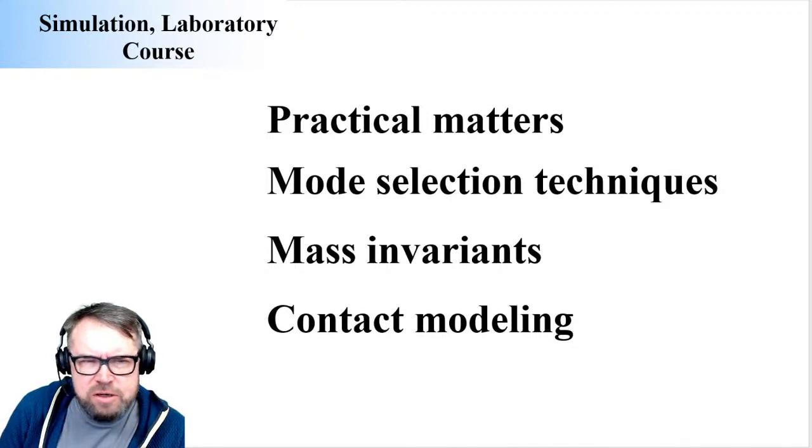Those two things are how to do this mode selection. So we know how to compute these assumed deformation modes. We know that we can do that by using an eigenvalue analysis, or if we want to be more advanced, then we can use the Craig-Bampton approach. But still, we haven't really discussed what next. If we have a set of modes, which out of these many modes are the ones that are most useful for us? These mode selection techniques, and the procedures to make good calls about how to select the proper modes, I would like to share with you today.